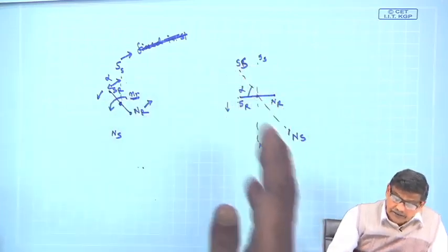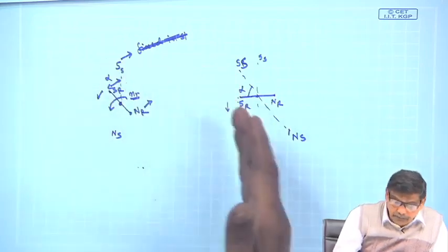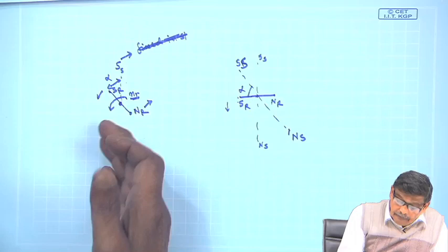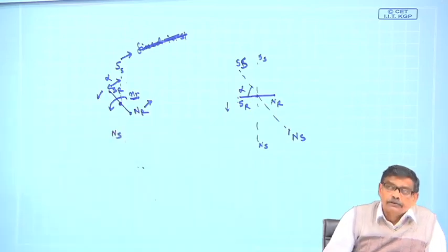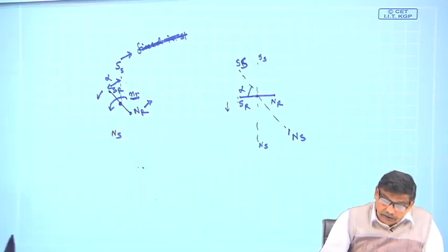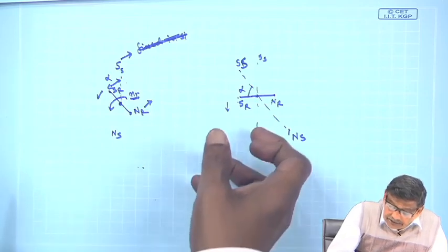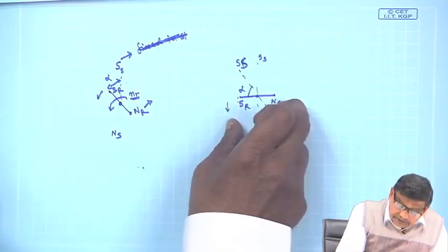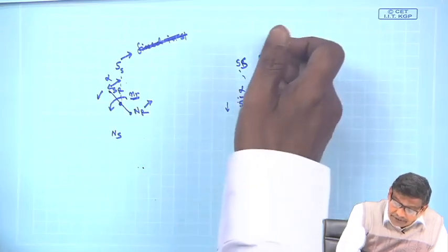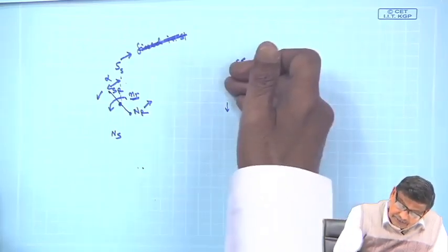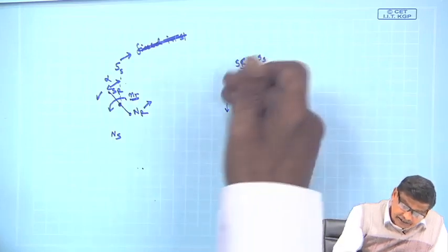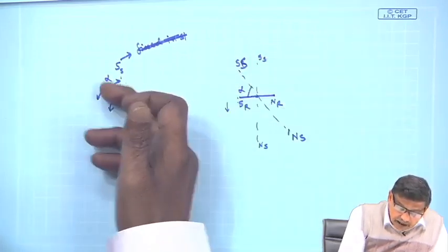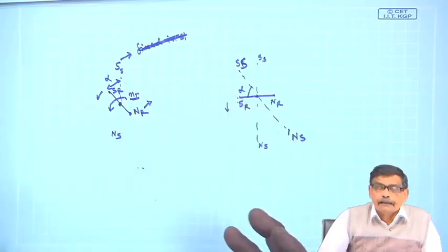So, if somebody says no, the same constant torque is to be produced as when it was producing here, then the answer to that question should be, you not only allow Sr Nr to occupy a new position like this, but also advance Ss Ns by such an amount that the angle between these two fields, alpha, remains the same.